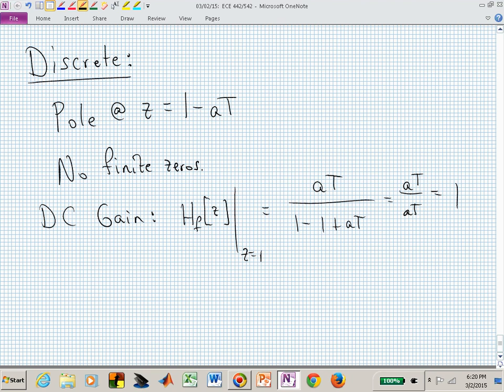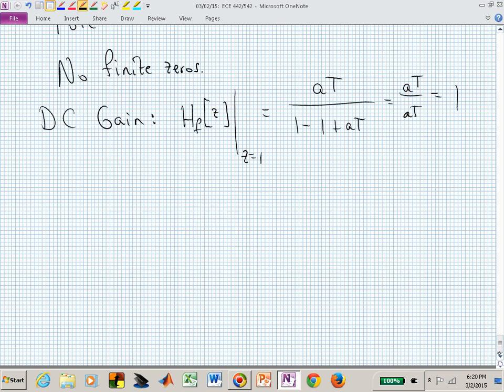Now you have a first order linear difference equation in the time domain. And that's corresponding to the forward rule of numerical integration. Let's look at another rule. And the rule was determined by how we approximated that little sliver in our integration. The next rule is the backward rule.